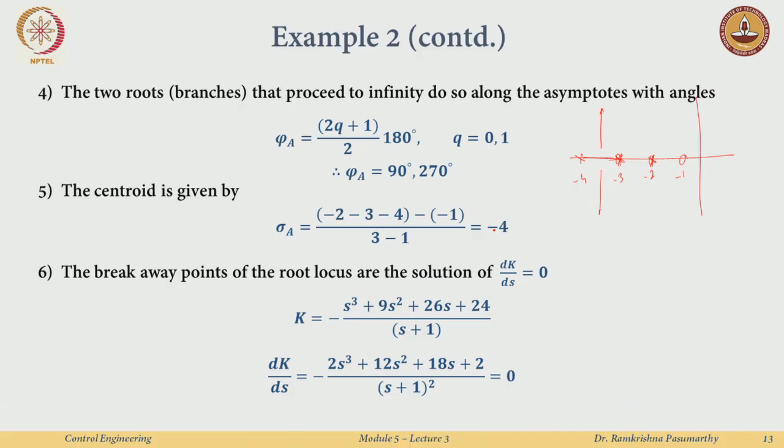Okay. Now, what I also know is that okay, now this is a centroid point, right. So, the asymptotes will be like this at minus 4. So, these guys will move and then they will meet these guys at infinity, and where do these lines at infinity come from? They come from minus 4. So, I know that one now, right. So, I will just remove this. So, I did not know which direction they go to infinity, but now I know that they go from minus 4.